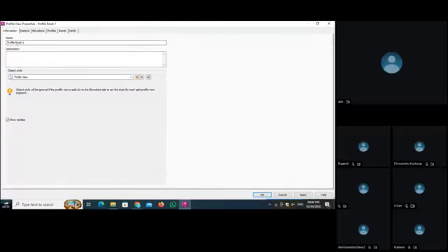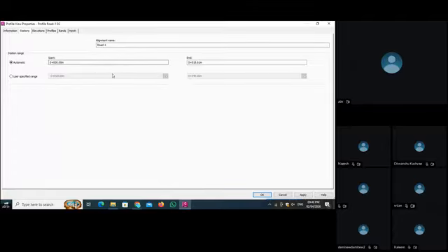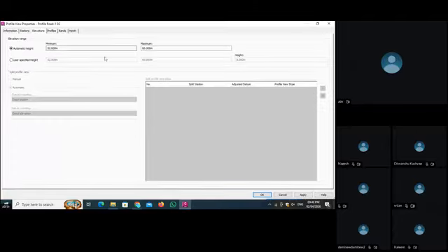If you want to change the name, you can say EG road 1 profile, or profile of road 1 EG, existing ground level. So you can change the name from here also. In station you can change the station if you want. Elevation also you can set your elevation.